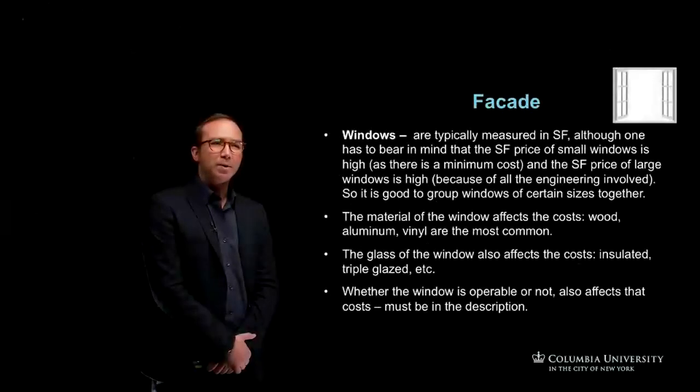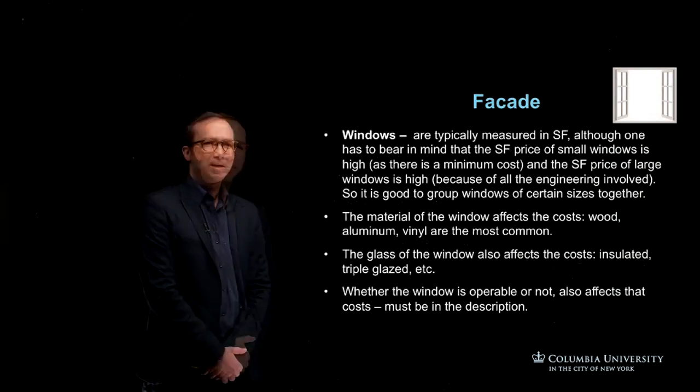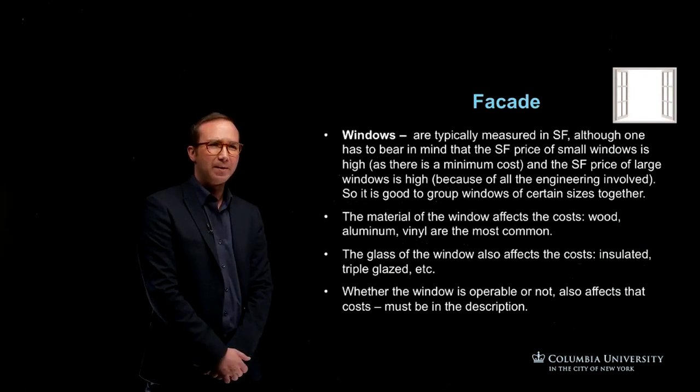So you're going to have other elements on part of your facade, and a few tips on other areas on how to measure these. So windows. Okay, so windows are typically measured on a square foot basis, although one has to bear in mind that the square foot price of small windows is high and the square foot price of large windows is higher. It's because of all the engineering involved there.